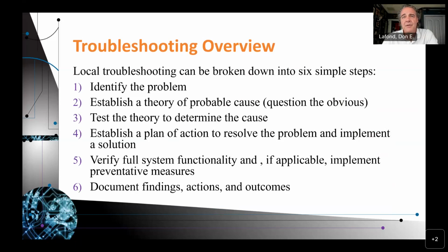Like I just said, for a monitor not coming on, the power could be disconnected at the back of the monitor, it could be disconnected from the wall, the circuit breaker could have tripped, it could be that it's not turned on, it could be that the monitor itself is broken, or it could be the video output to the monitor, not putting out video. A lot of possibilities for something as simple as the monitor not coming on.